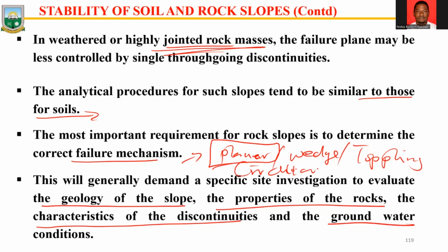How durable is the material? So if you get to know the durability of that material, how it's going to react to weathering, whether it is going to weather fast or slowly, if you get to know some of these properties of the material you are transporting to your waste dam, then it will help you batter the waste dam very well and get good slope angles over there, and that will ensure safety.